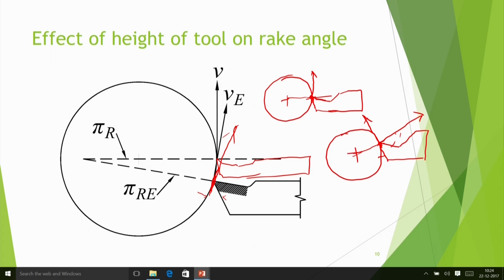So with cutting tool angles, it is not that a particular tool is there and therefore all these things are fixed. The way it is mounted will also change the geometry. The tool is the same, but I can have it inclined, I can do this. That means on a tool holder, I can mount it in such a way that its tool angles can change. That point also has to be kept in mind.